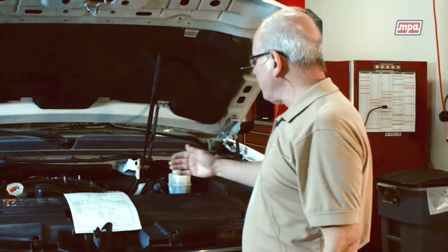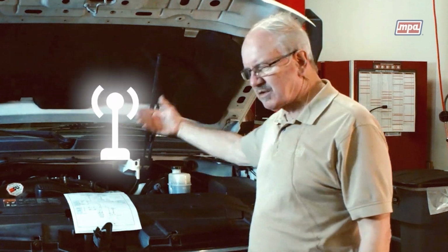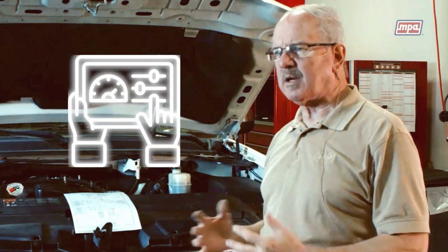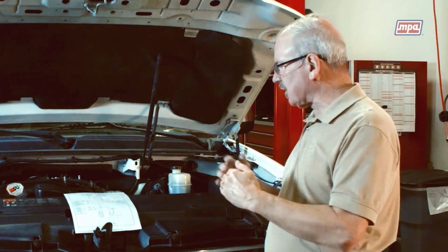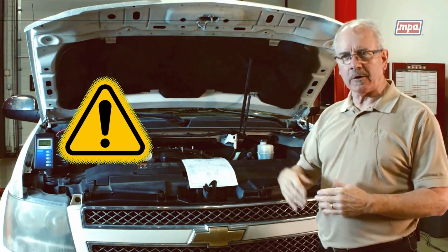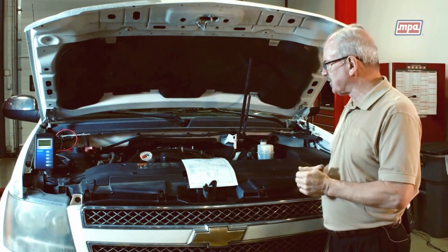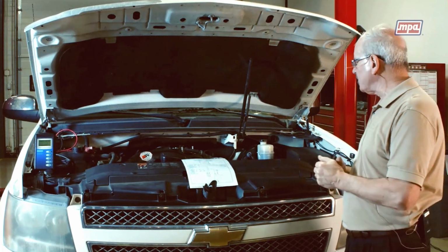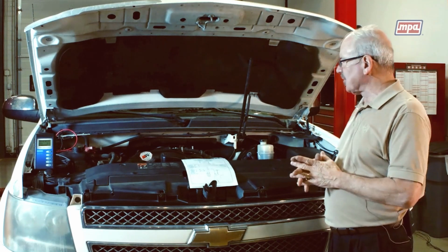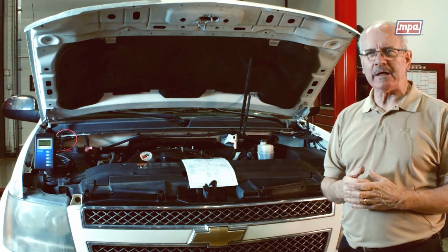The F circuit, as I mentioned, is the feedback circuit that's going to send a signal to the PCM so the PCM can monitor the alternator load on the vehicle, and then it looks at that circuit for any signs of fault or failure in order to generate that P0622 fault code. And using a scan tool, there are a couple of quick things you can do to look at that circuit, test it, and verify the integrity of it.